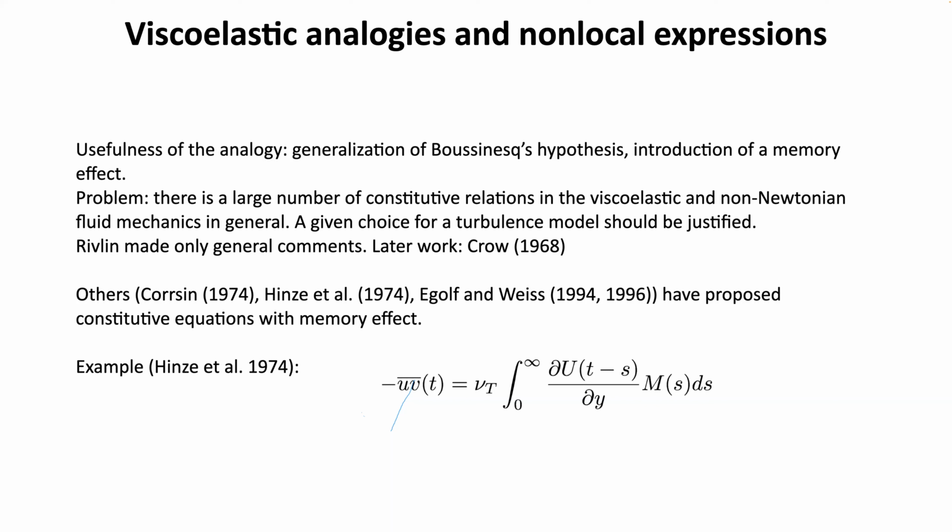I do have one question. Maybe it's on the same line of what was discussed before with the Reynolds stress tensor. Recently, they have become more and more popular. There are models that include one model per each term of the Reynolds stress tensor rather than using the Boussinesq hypothesis, right? And I always read the argument that they are too expensive, and that's why the Boussinesq hypothesis is more popular for commercial software or for industry, because it gives rise to a less expensive model.